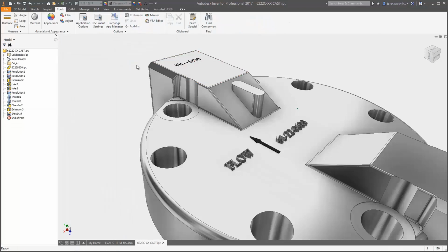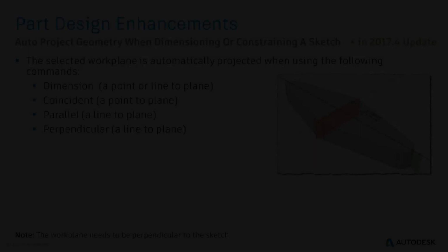I didn't explicitly mention that you have two additional 2D Sketch mini toolbar options available as of 2017.3. The Share Sketch and Make Sketch Visible commands. This saves you time to navigate to the browser and to do the same actions on the context menu.